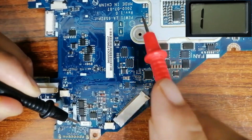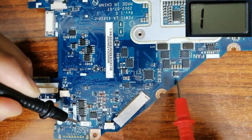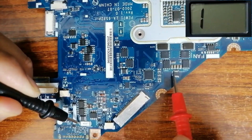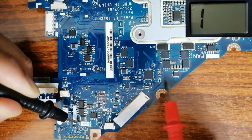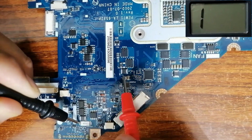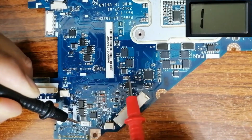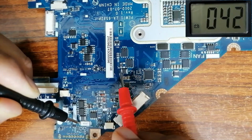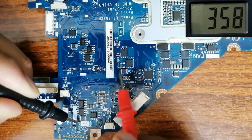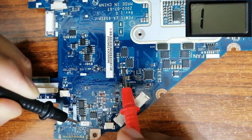Let's check, for example, the CPU circuit. This is the input. This inductor always means input. Do you see? We have low resistance. It means this point is connected with this point. Let's check this circuit also. This is the north bridge or chipset circuit. As you can see, this point is connected to this.